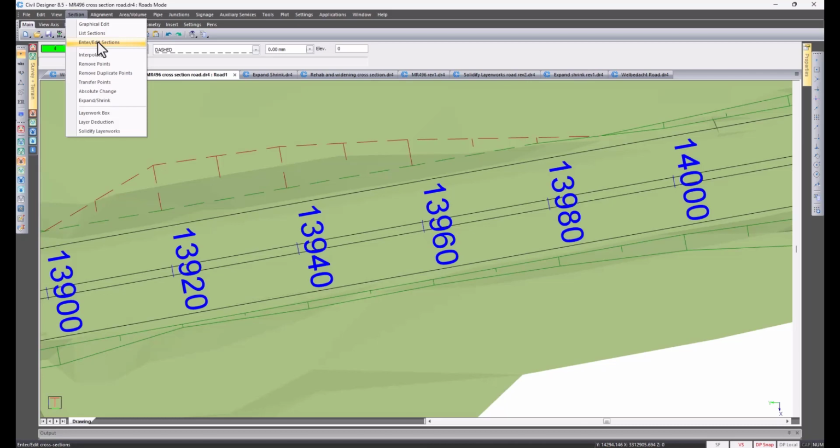And then for roads done with the traditional cross-section method, you can identify or edit your point location codes and IDs. IDs are generally a specific number assigned to a cross-section point, and then use those IDs and point location codes for displaying plan lines in your plan plots or plotting specific levels, for example, on a cross-section.